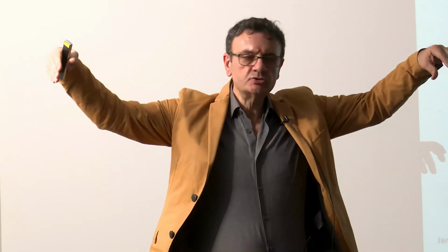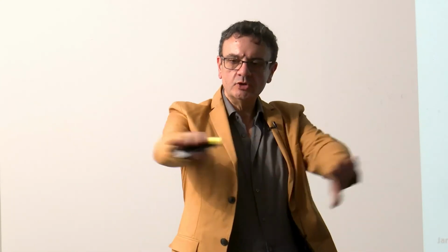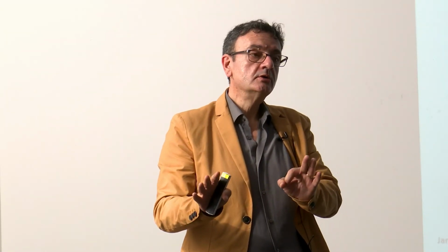Mr. Mahindra, if you let me, I will explain this point. It depends on the machine, number 1, on the location, number 2, and what is underneath, number 3, and on the structure itself. So all these things play a role. Now suppose you have a really noisy machine, and underneath you have an office space. If a consultant comes and tells you, I'm just going to put a pad under that noisy machine, tell them that is not enough. Because in addition to the vibration that travels through the structure, there is noise coming through the air, and that's going to go down. If you do not close the whole area, that noise is going to pass. There is no way around that. Either get a silent machine and then put a pad underneath for vibration, or if the machine is noisy and nothing can be done about it, then you need to insulate the whole area.